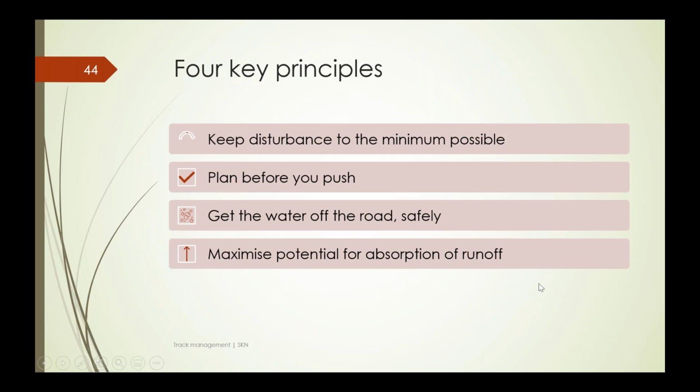Drainage practices, all the different forms of drainage that we're talking about, are all about getting the water off the road safely. So all those various practices, mitre drains, culverts, drainage diversion banks, are all about getting water off the road and trying to minimise the opportunity the water has to cause erosion.